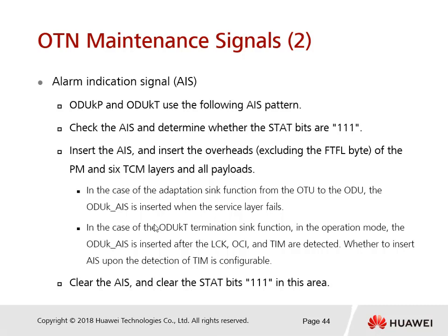In the case of the adaptation sink function from the O2 to the ODU, the ODUK-AIS is inserted when the service layer fails. In the case of the ODUKT termination sink function, in the operation mode, the ODUK-AIS is inserted after the LCK, OCI, and TIM are detected.